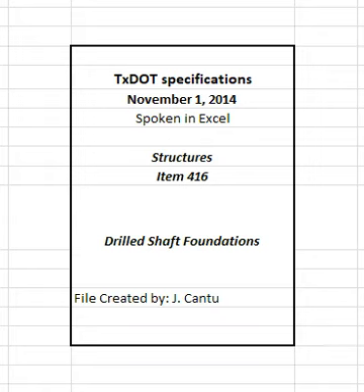Extract casing only after placing the concrete to an appropriate level. Maintain sufficient concrete in the casing at all times to counteract soil and water pressure. Rotate or move the casing up or down a few inches if necessary before and during concrete placement to facilitate extraction of the casing.